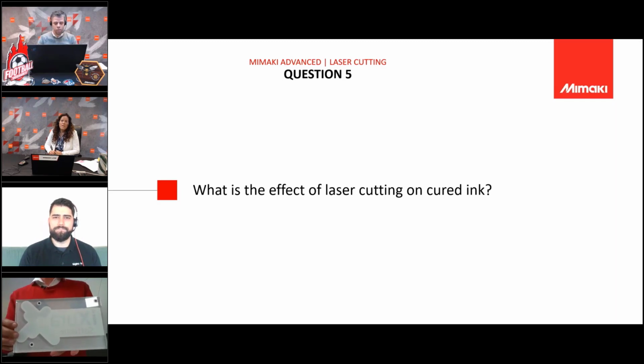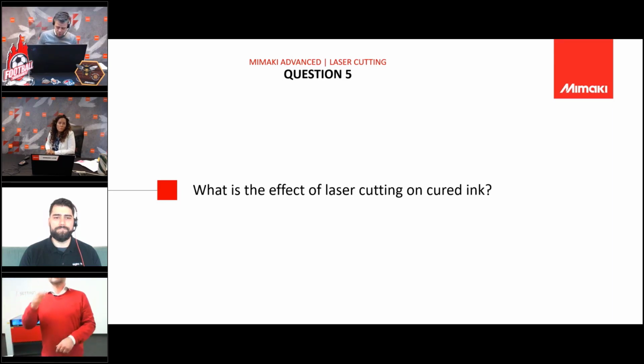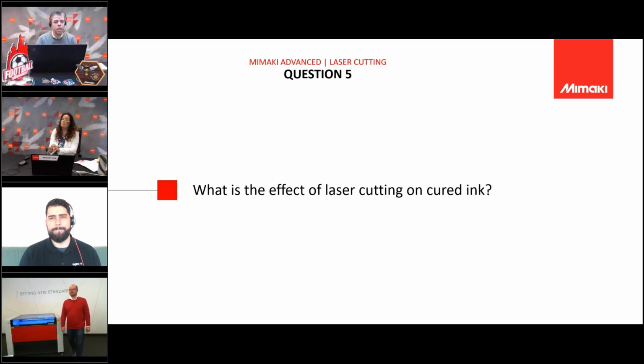Maybe Rens can comment on this. Yeah, Rens, how easy is it to prepare those files? Is that difficult? No, not really. For the job control, we have a special function in our rastering tools, so you can easily export your cut files for the Trotec. So it's already implemented in our software. If you have the cut lines and you work by color, for example 255 RGB red, it will recognize the cutting line automatically, and you can apply different colors for different cutting settings, and the marks will be detected automatically. It's also shown in the extended movie we'll put online shortly, and it's a couple of minutes. It's really easy. A little bit of skill with software like Illustrator or CorelDRAW, and you're done.